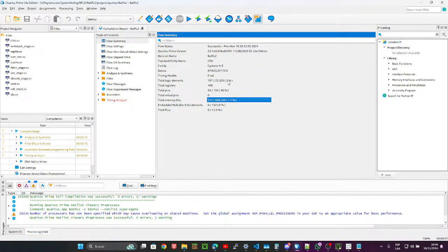Yes. So you replaced program memory for a prototype. This is where program memory would go on a prototype, with Bram for cache. And then if there's a miss, you stop the clock of the CPU, right? Yes. And then you do a state machine fuckery to bring in more data from external memory. Yes.